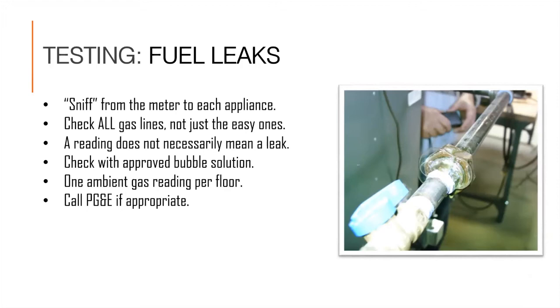And if the bubbles begin to percolate or even expand like what you see in the picture, you got problems. Oftentimes, though, even when we check with bubbles, it's actually not enough to create bubbles. So be mindful and diligent about it. We also are looking for ambient gas readings at each level of the home, and be aware of and call PG&E if appropriate.